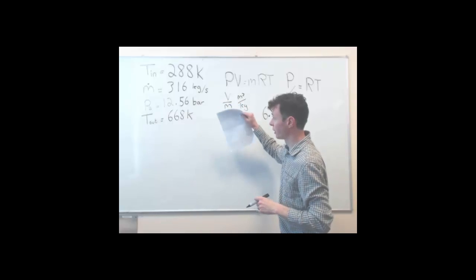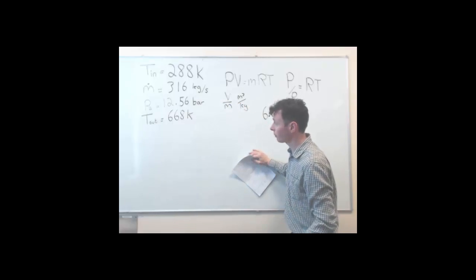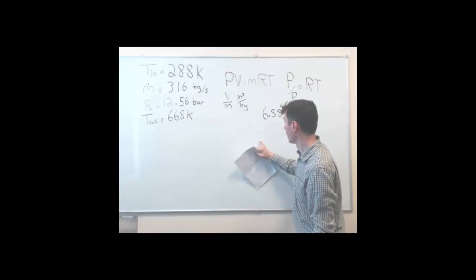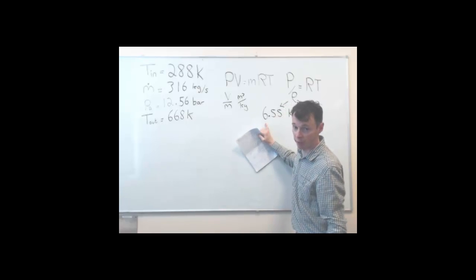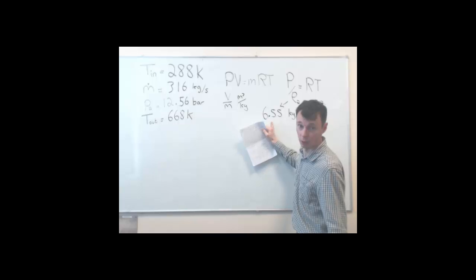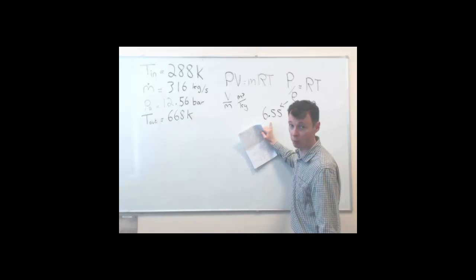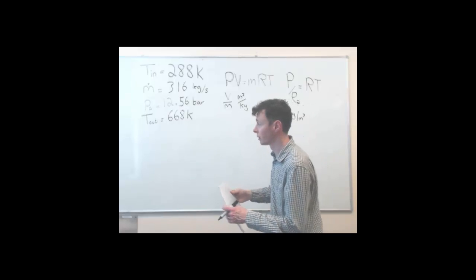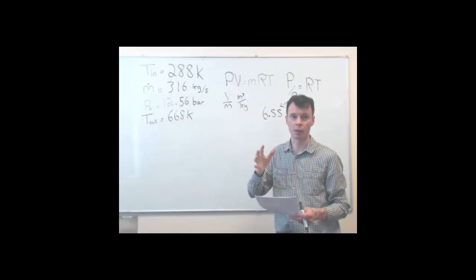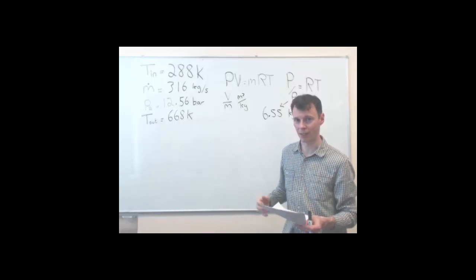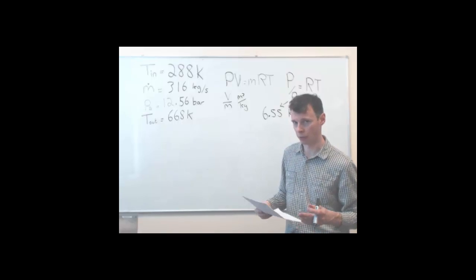If you look at the compression ratio, in terms of the differential pressures in and out, it's reasonably high, and standard density of air is about 1.23 kilograms per meter cubed. So this is a reasonable amount more. If it was less than 1.23, I know I've gone hideously wrong somewhere. Okay, so as I've always said, you can start to learn to appreciate the sign and the magnitude of your answer to see if you're in the right sort of ballpark.